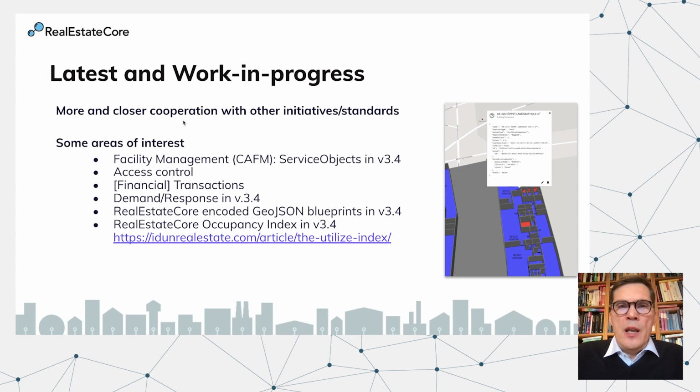Another thing that we have done is that we have created an occupancy index. And there's a link to a blog post, which is basically a white paper that describes the algorithms and there is no secrets, all the mathematics. But this enables us to take any sensor that we find in the buildings, peer sensors attached to a BMS system, AI-based people counting cameras, footfall cameras, IoT sensors, anything, and normalize this to RealEstateCore into presence that creates an occupancy index. And this, of course, makes it possible to break silos between systems, reuse all your installed sensors you have in the buildings in order to understand how the buildings are being used for planning, for cleaning, for should we, do we need to run the ventilation as hard or the cooling as hard? I mean, all the people have already left the building, etc.